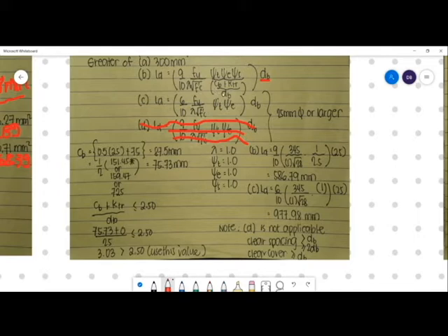So let's solve for C sub B plus KTR over dB first. C sub B is from the center of reinforcement to the nearest concrete cover, 0.5 times 25 plus 75, 87.5. Or 1/2 times 151.45. We have three different center to center spacing, 151.45, which we solved earlier: short direction, long direction, and the center band.